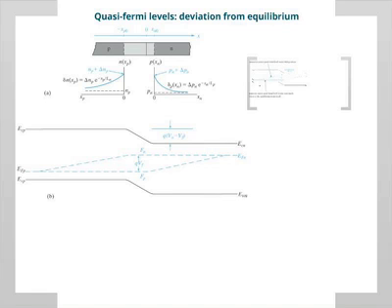This point, there are many more holes. And remember, this is the p-type. Sorry, many more electrons. This is the electron curve. Minority carrier concentration exponentially decreases in the p-type material. Of course, let's start with far away. Far away, the electron concentration is the same as under equilibrium, right? Because all the extra electrons have diffused and recombined away. So far from the junction, you would expect the Fermi level to be the same as before. P-type, so it will be close to the valence band, right? That's obvious. As far away, the excess electrons have disappeared.